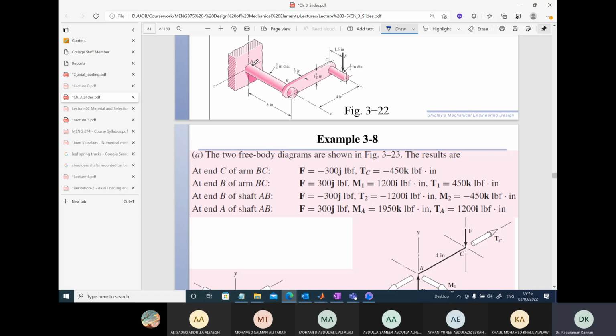If you want to calculate the moment acting at A due to the force F, then we have to solve it in vector format by drawing, for example, the vector R here, and then figuring out R cross F. Using the R cross F formula in vector format, we will exactly know what kind of torques and moments act at that point.